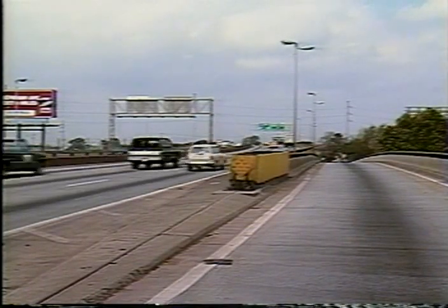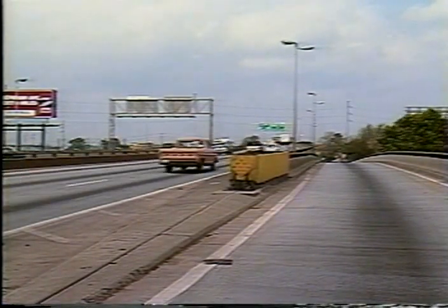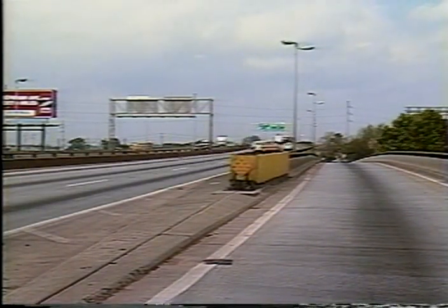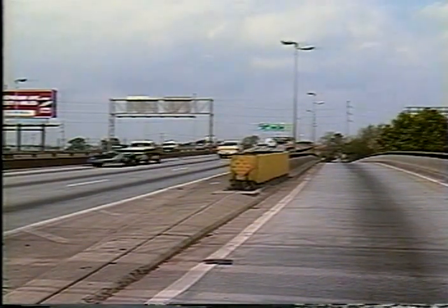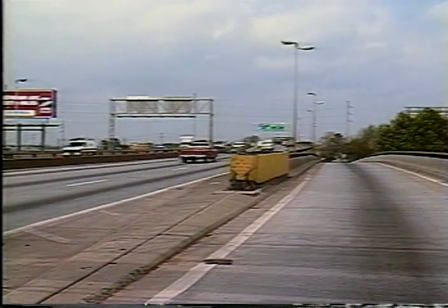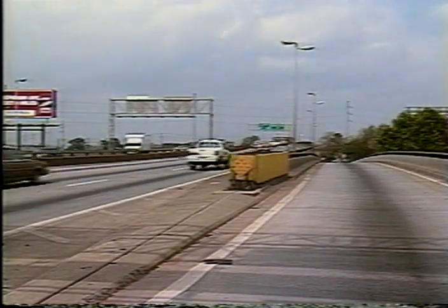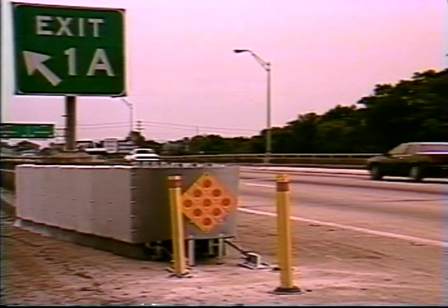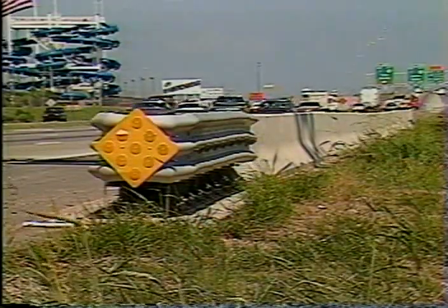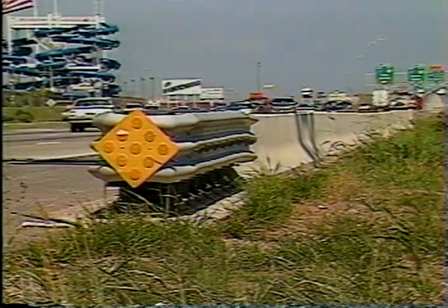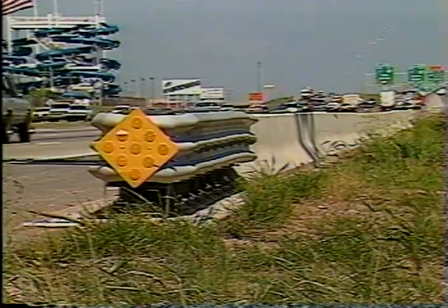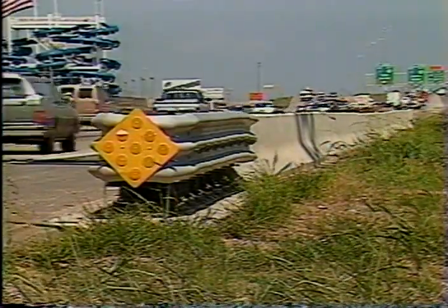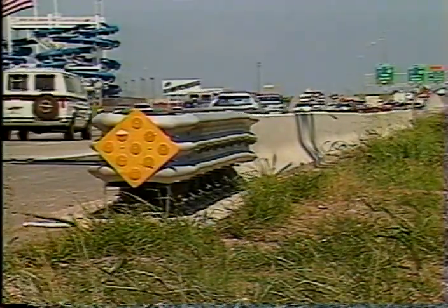At times, there simply will not be an appropriate end treatment available to meet a traffic safety need. That's when a combination of both a barrier system and a crash cushion system might do the trick. Crushable crash cushions can be used with some special needs, but the most common use of combining crash cushions with end treatments will be when they're used with rigid systems, such as the concrete traffic barrier.